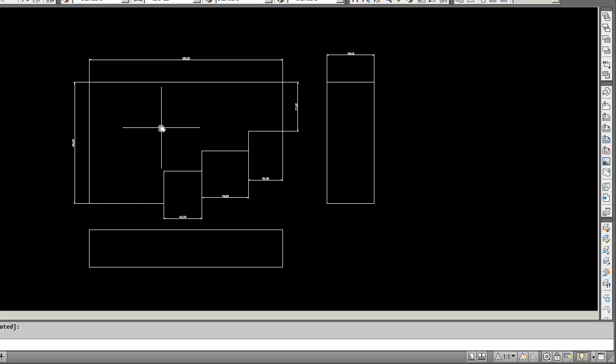Do you know what the scale factor is? It is the drawing size to the actual size, or in other words, we can mention it in the form of a fraction: if you print the drawing and measure on the drawing, that size divided by the actual size of the object is the scale factor, expressed as a fraction value.